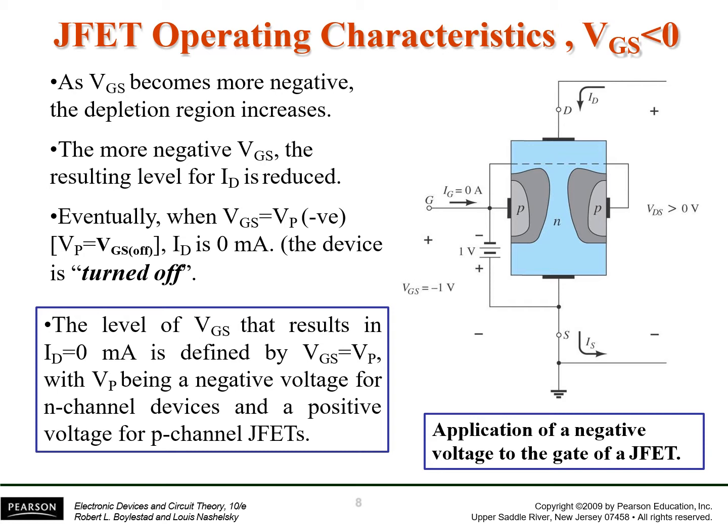If we further increase the value of the negative potential between the gate and the source, the saturation current would reduce further, and a time would come when ID would remain at 0, whatever the value of the voltage between the drain and source is.